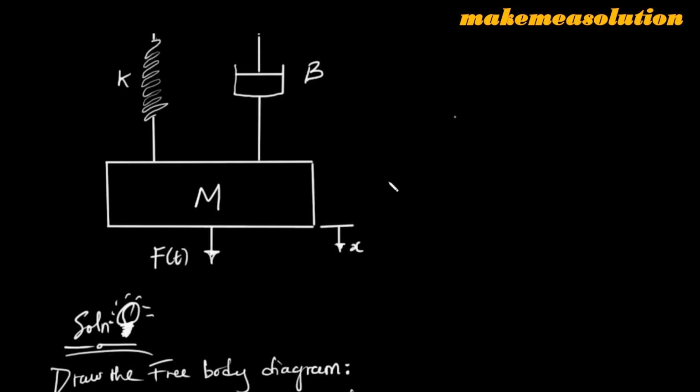Usually the reference direction should point in the direction of the displacement, or in the direction of the applied force. If there is an applied input force, let the reference direction point in the direction of that input force. So in this case, our reference direction is down, so down is going to be positive. You're not thinking that usually down is negative. This time around you've changed your down in your mind to positive. So this is your reference direction. With this, we're going to draw what?